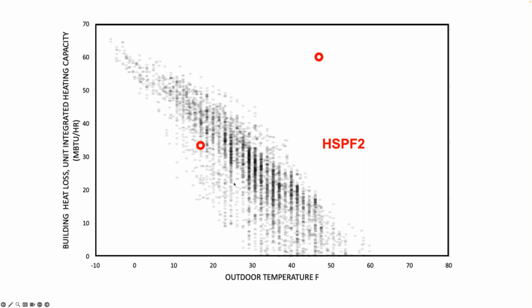So to resolve this, Addendum 82 aims to flesh out a much more comprehensive performance map based on the best available data sources. This means establishing performance at more temperatures. So maybe a minimum temperature, a 5-degree point, which is often characterized, and then an extreme point where the equipment probably doesn't operate very often, but the compressor probably also has a maximum capacity there. And so there's a full range here.